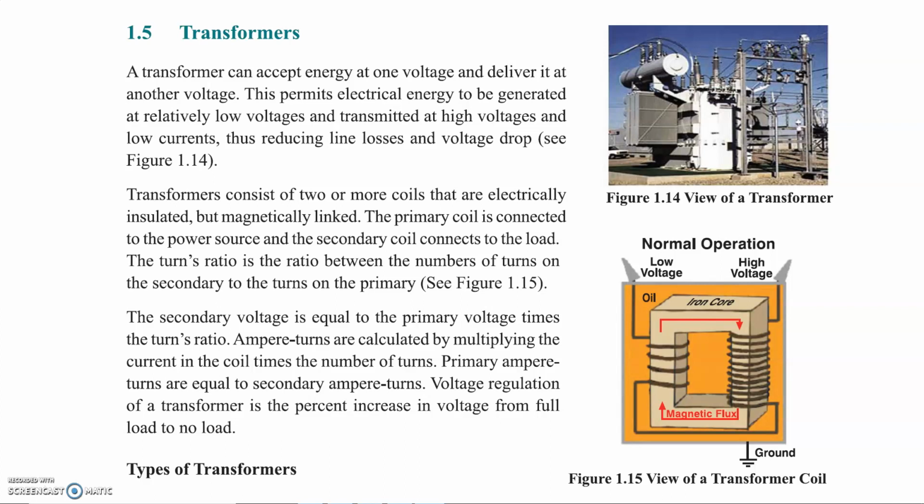So if the primary side number of turns is, let's say, 5 and the secondary side number of turns is 10, then the voltages in the primary side and the secondary side will be related as 2:1, that is 2 divided by 1, because the secondary side has 10 turns and the primary side has 5 turns, so 10 divided by 5 is equal to 2.